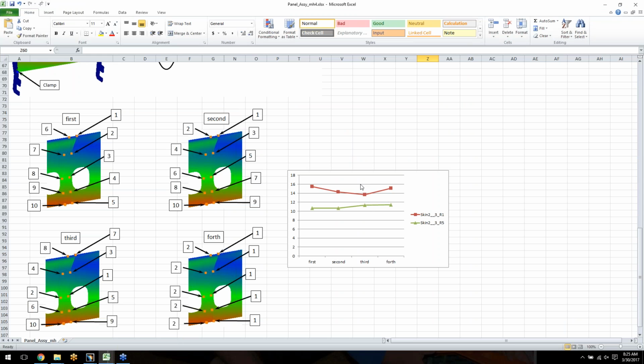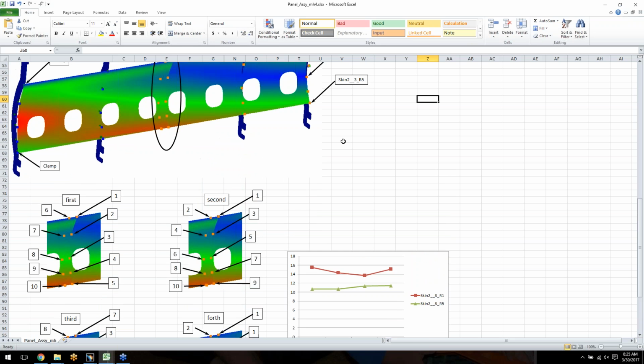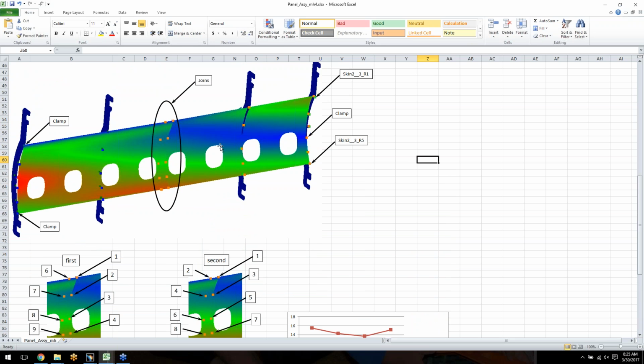In my opinion, this is where the two corners are very close to each other. So the top corner and the bottom corner are not twisting too differently from each other. So I would go with the third scenario. The second scenario is not too far away from it. And keep in mind, this is all based on how the parts are constrained when they're joined and how the parts are still constrained after releasing everything.